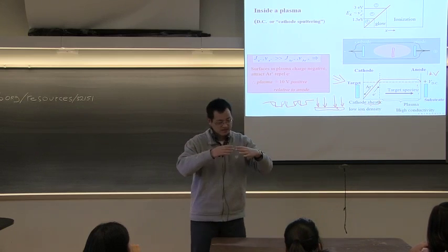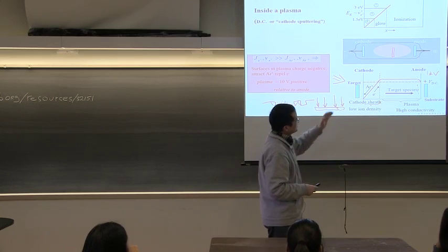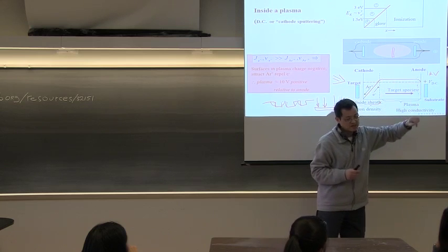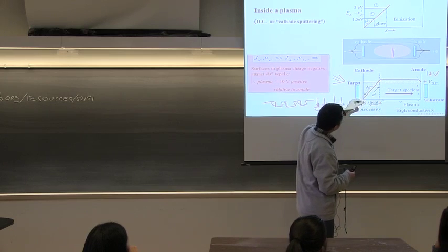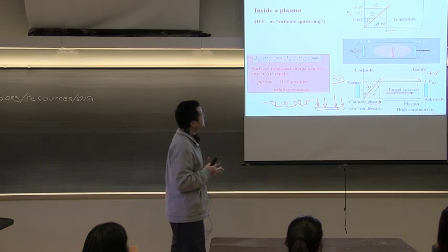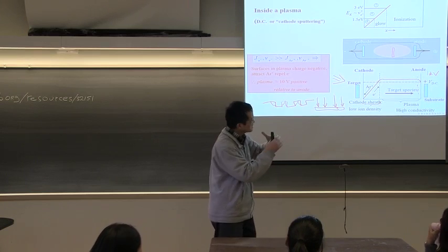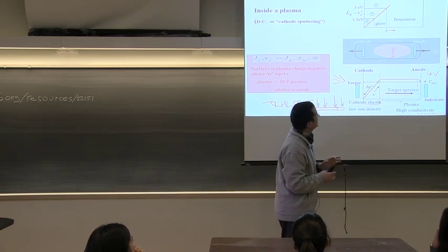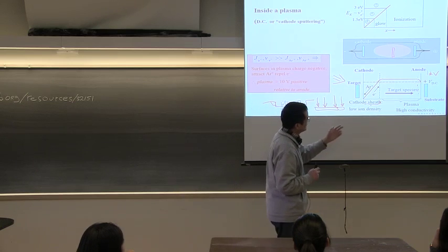As we have discussed, you can think of the sheath as the area where we kind of enclose the plasma. And if we look at the potential, inside of this glow region, in the plasma region, the potential doesn't change. So basically it is more or less a neutral region, but there are electric fields and potentials built up very close to the target or the cathode region. We will try to explain what it is in the next slide. But basically, the plasma will establish a voltage difference, a potential that goes towards the target.